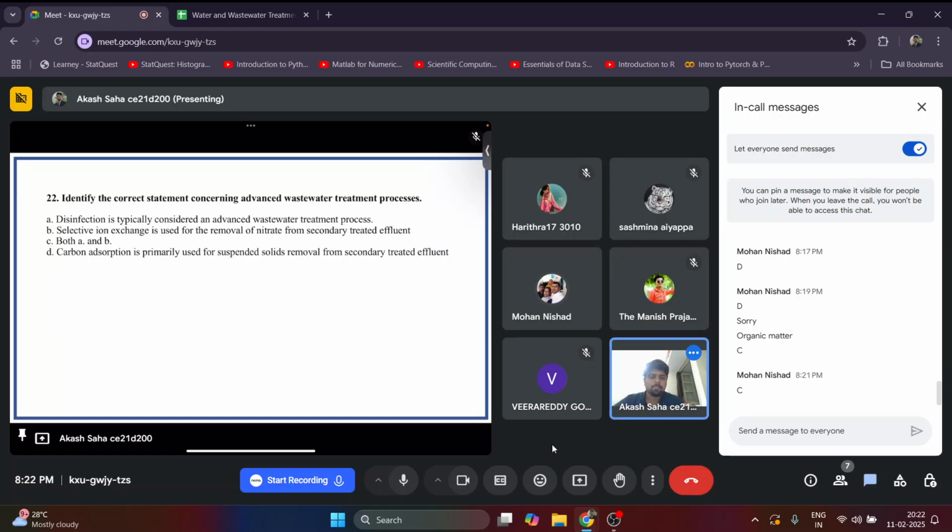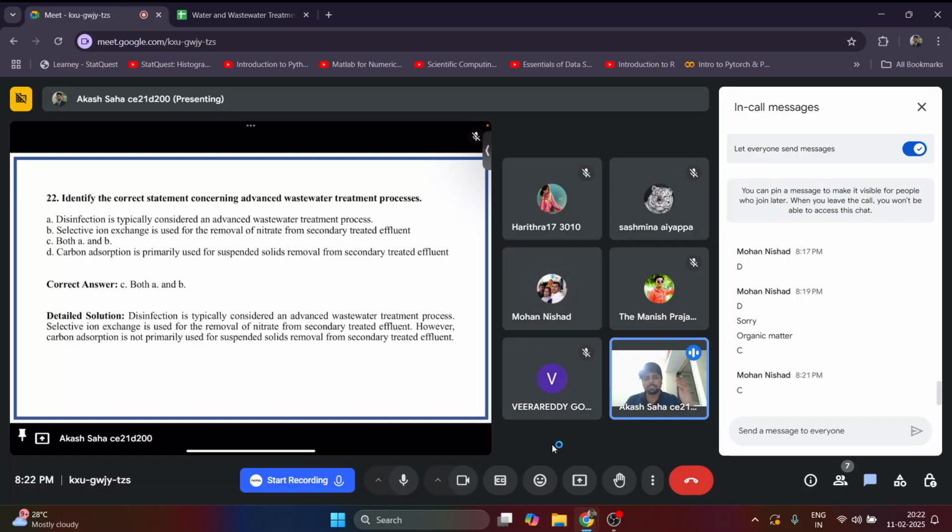Okay, for suspended solids removal, if it's inorganic, then we use bigger size inorganic particles removal like the grit chamber or the primary sedimentation tank. Okay, so suspended particles are taken care of in that aspect, or maybe some filtration processes also. But with carbon adsorption, we try to remove some pharmaceuticals or some dyes, other chemicals, toxic compounds, heavy metals, things like those. Okay.